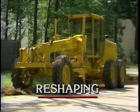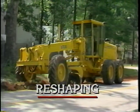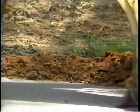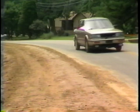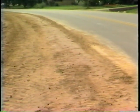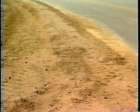The first type of shoulder maintenance is reshaping of the shoulder. No additional shoulder material is added and no excess shoulder material is removed. Reshaping restores the desired cross-section and slope of the shoulder. The end result is a smooth shoulder with a smooth transition from the edge of pavement sloping down to the front slope of the ditch.